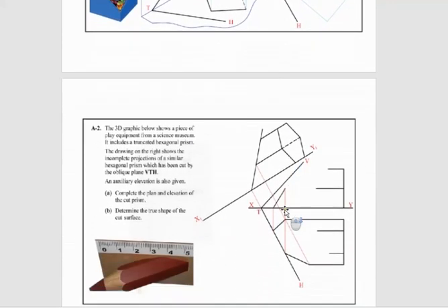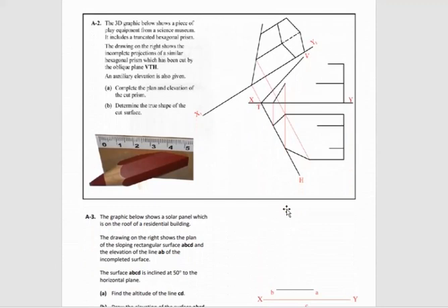Now the next question here is again a more traditional oblique planes question. What we're given here is a solid being cut by an oblique plane, partial plan is drawn, partial elevation is drawn. So we just need to finish the drawing of what's being cut. So basically in this question here is we have points up here in the auxiliary, we bring them down, we mark them in plan here, we complete the elevation or the plan of this, then we bring the points up to elevation and complete the elevation.